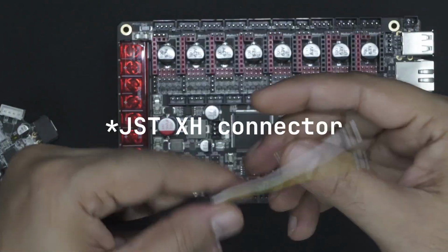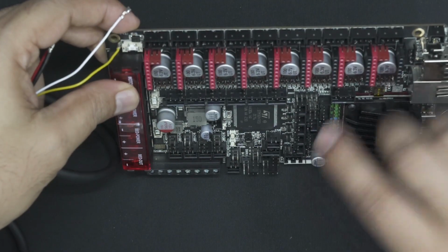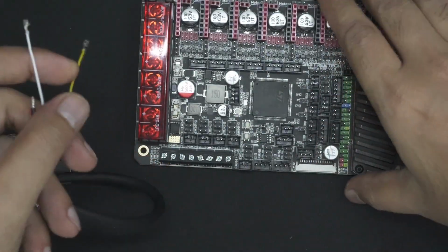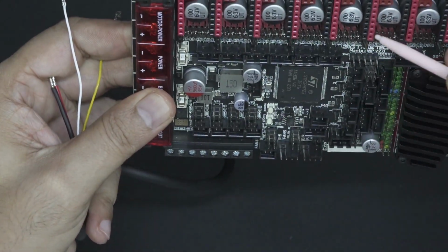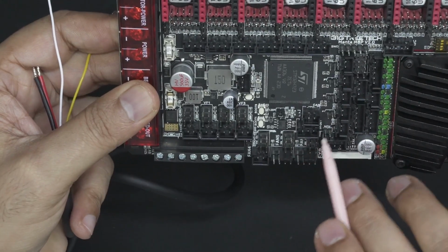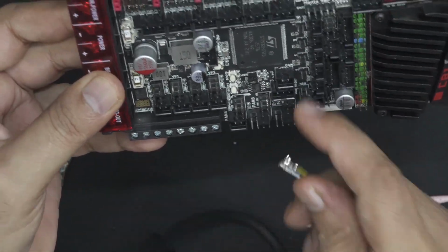And then we need to install the terminal connector over here. So for this board, I need to look which one is CAN high and CAN low. Let me just look for this and come back. Yeah, okay. So the CAN high is yellow over here. So this will go on this side of the pin. Remember, the driver pins are facing away from me, and this terminal block is facing towards me. So from that point of view, this is the pin where I will connect the CAN high. That is, the yellow cable will go over here.